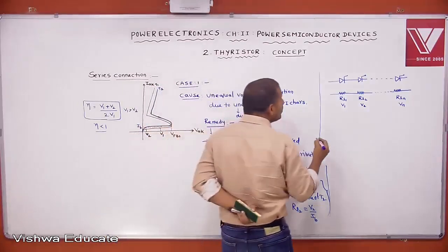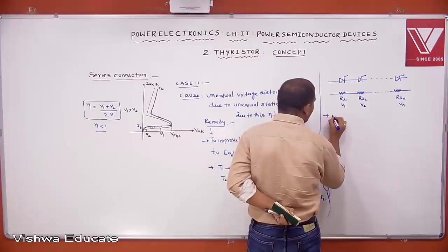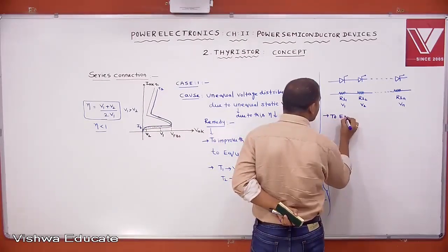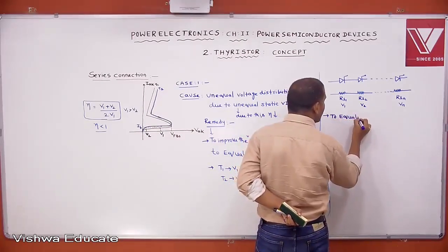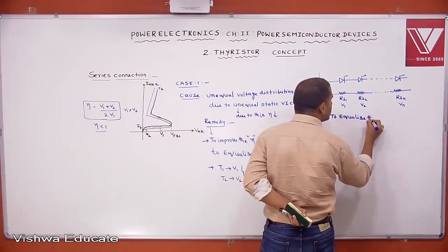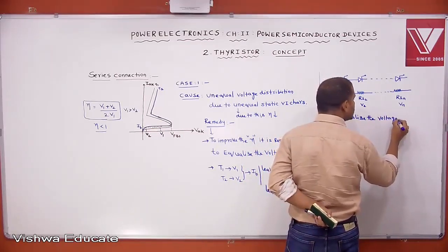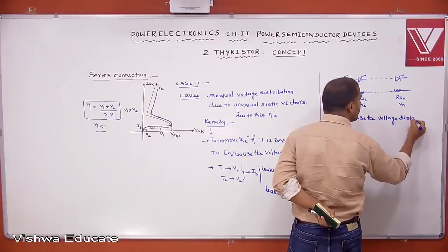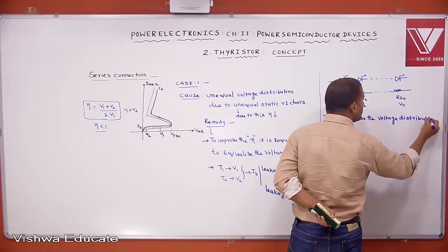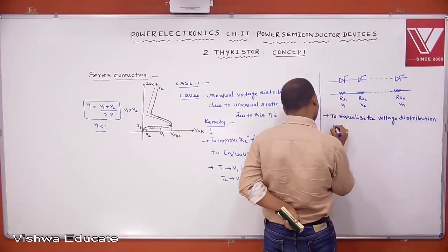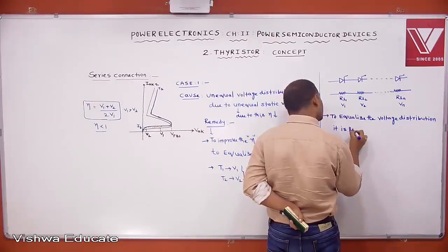That means to equalize the voltage distribution, it is required to equalize which one? The leakage resistance.